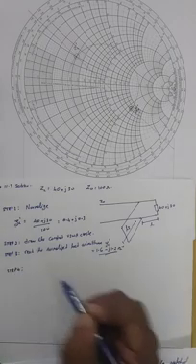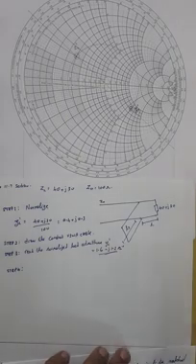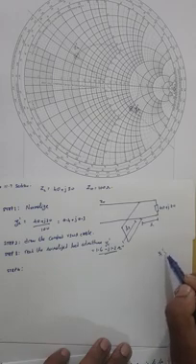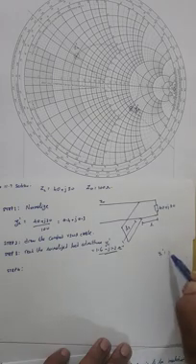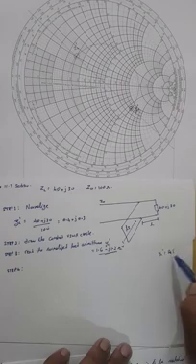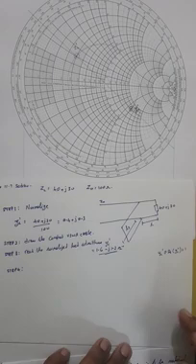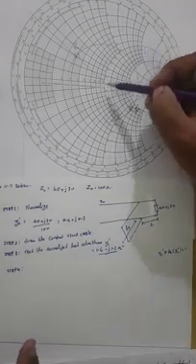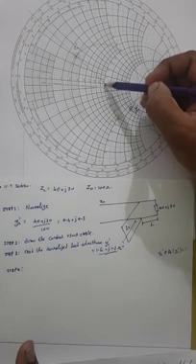Now our step 4 for impedance matching is very interesting. As we discussed in the theory part, we need the real part of the normalized load admittance to take a value of 1. Highlight the unit circle, or the circle which passes through 1.